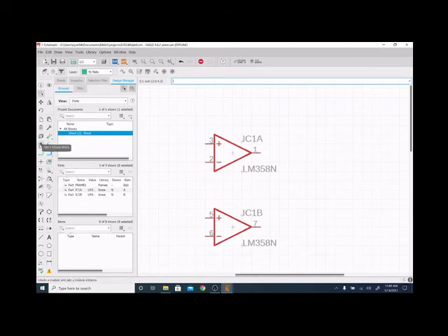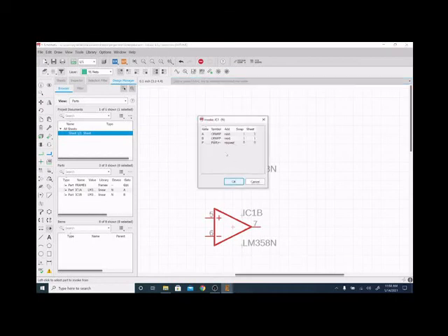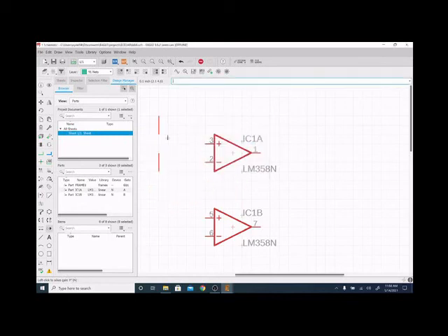So I need to find that again really quick. Shoot, there it is, invoke. Okay, so we use the invoke command and we click on the anchor point, that little crosshair right there. And it says, okay, what do you want to pop up? And we say we want to invoke the power pins. And now we have these beautiful power pins floating around, so I could just click them right there, and now we have our pin 4 and 8.